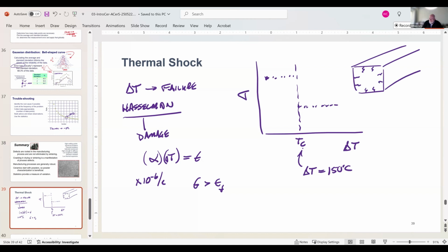And the reason is that the surface cooled and the interior remained hot, and the cracks would propagate to the point where this had enough time to come back up to the same temperature basically. So they create enough strain. These cracks on the surface, which look like this, are all over the surface, right? They became the critical flaws. That caused this drop in the strength in the system, when you form these cracks.